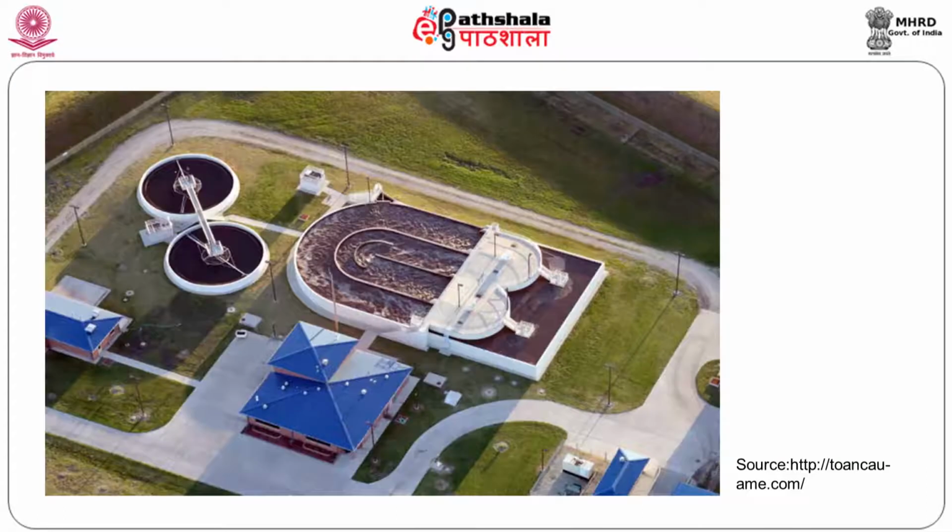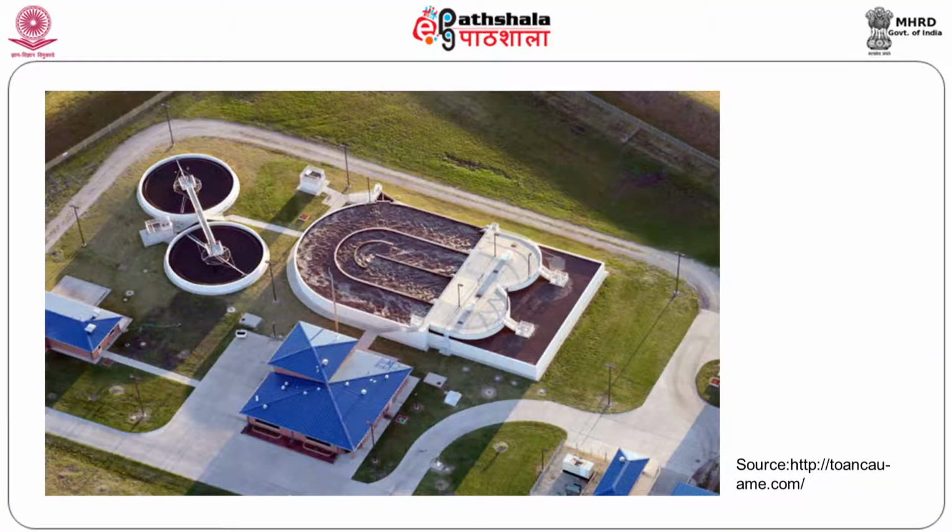So, if we analyze the performance of oxidation ditch, here we are operating the reactor at high MLSS concentration. At the same time, the solids retention time is high when compared to conventional ASP system. Here we are keeping solids retention time up to a maximum level of 20 days. Applying this technology for industrial application, we can keep solids retention time up to 48 days. So, by operating any biological system at high solids retention time, in addition to carbon oxidation, we can achieve nitrification.